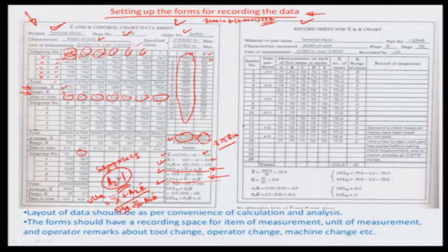So, having said that, these are how the UCL X-bar and the LCL X-bar vary, and then we will also have the UCL R, which is basically the upper control limit of the range chart. So you have a chart describing the ranges, and you have a chart describing the X values or the quantitative measurements. Here, when you do a subgroup of less than 6, the Shewhart method says that for subgroup size less than 6, the D3, which is recording the lower control limit, is actually 0.